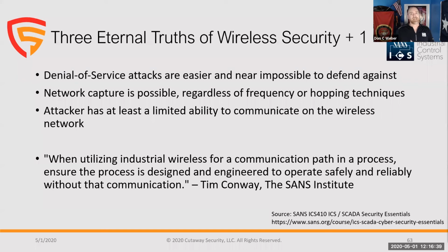But anybody implementing wireless needs to also consider this one, which is if you're implementing wireless within your process, you need to ensure that you have determined whether or not that process can run without the communications that those radios are providing. I couldn't pick a better slide to put this in, because that, in my mind, is another eternal truth. We need to make sure that our processes are resilient when these communications are not available. So thank you, Tim.